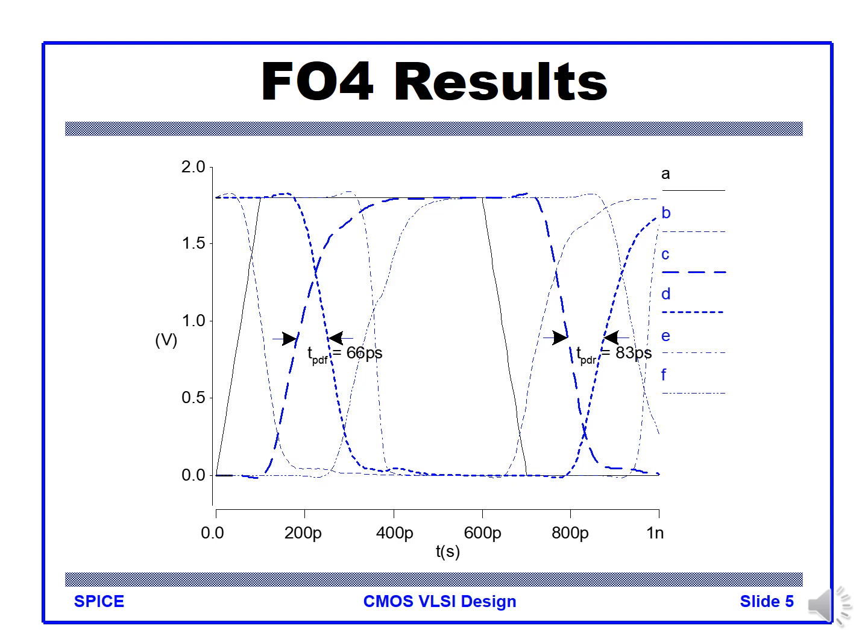this is the actual delay output. So we have A, B, C, D, E, F. A is the input, right? A, and B is here. B, C, D, E, F, right? So in this example we applied a little realistic rise time, right? That is similar to the internal output. Here it is a little faster, then a little slower, and slower, right? Finally it slows down, right? Compared to here and there, this slows down to a practical value. So we measure this passing half VDD, two points, right? This delay is measured for each.